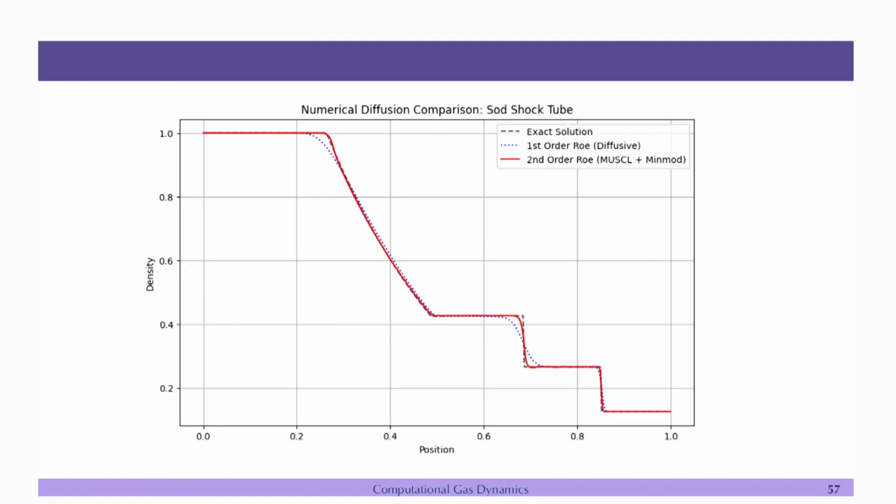that you note close to the discontinuity. For example, if you look at here, so this is where we stopped in the last class. Okay, so here, if you look at the blue curve, they are highly dissipated here and here. So, the question is, can we improve these predictions, right? So, one way is that you make the grid size finer and finer, and then the accuracy will improve.